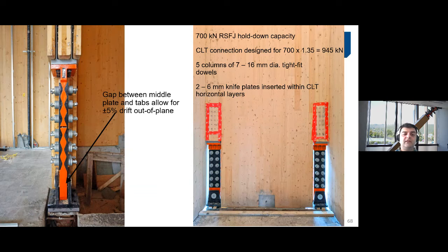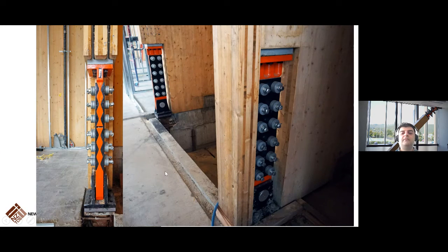This detail could be interesting: how to connect the units to the CLT. Normally in North America, they're very comfortable using knife plates and then using dowels. But in New Zealand, there are different solutions. This is not that common. I hope it becomes more common. Gluing rods are common in New Zealand and have been used in some projects.